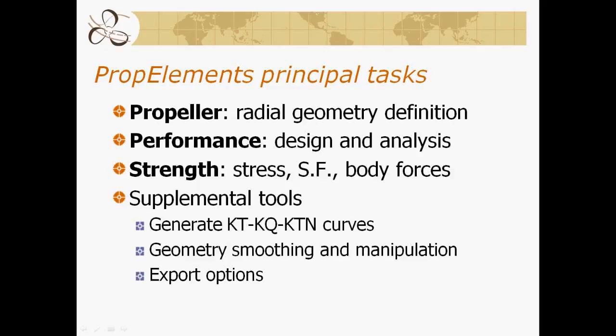We have a variety of supplemental tools that are useful. One is the generation of KT, KQ, and KTN for nozzle curves. There's geometry smoothing and manipulation of the shapes for the user experience of a design. There's also a variety of export options to make PropElements a tool that can work in conjunction with other tools, such as our PropCAD software for geometry definition, for example, and also NavCad, where the performance curves, the KT-KQ curves, can be used as part of a NavCad calculation.